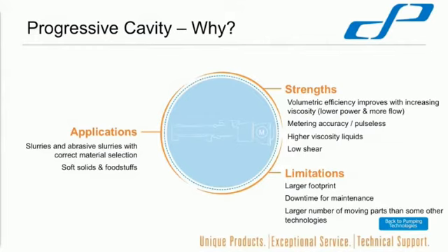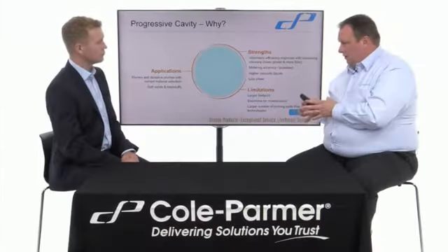Again, we were talking in another video about centrifugal pumps and potential damage. These don't cause the damage because they are that low shear, and they can be food grade, so you can pump through to clean them, and you just have to have a clean down regime. They can be industrial grade, you can have industrial motors. There are many, many variations.